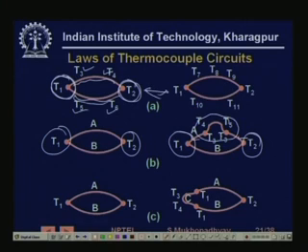The third point is basically a similar thing, only that you are now opening out the junction itself. So rather than having a junction, you can have an extended junction. You can call this one the junction, though it is not a physical junction. The junction is actually through another, arbitrary metal. Even then the EMF is the same.